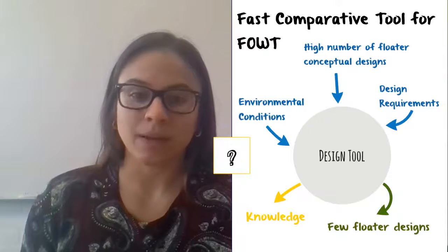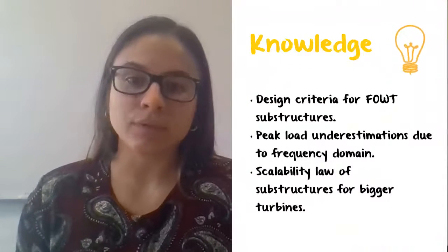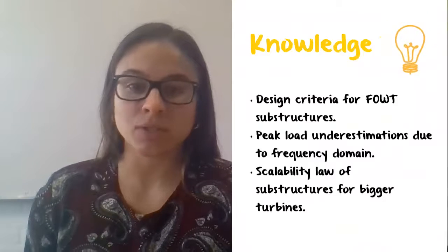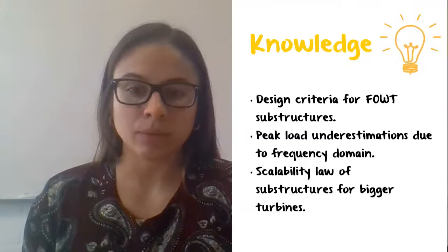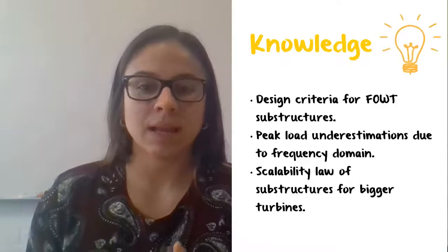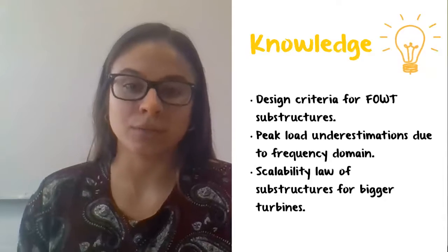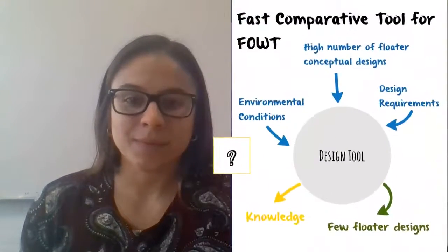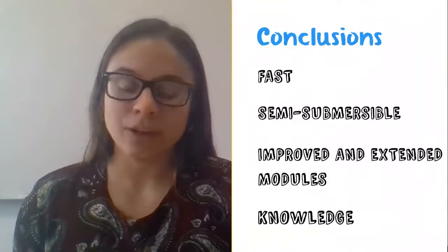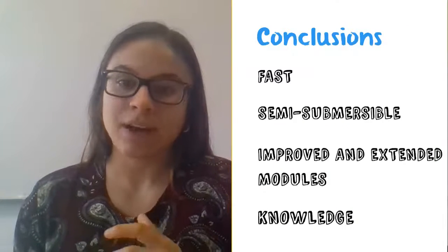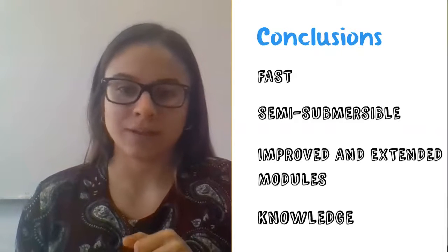So with this tool, we can also obtain some knowledge, such as defining the design criteria for floating offshore wind substructures, studying the peak load underestimations due to frequency domain, or obtaining some scalability laws for the substructures for bigger turbines. So I think this is a quite interesting tool from which we can obtain a lot of knowledge, and it's fast, focused on semi-submersibles, and with improved and extended modules.